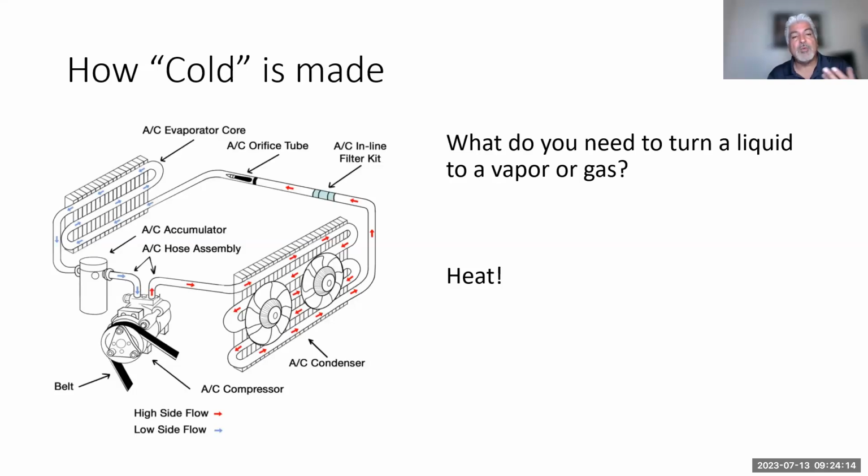What do I do, right? So in this case, it is a wise idea to look at the accumulator. And on most accumulator systems, it is the easiest component to remove and look at. So we can drain it to see the oil content, right? We can drain the oil. So let's say the system takes 8 ounces and I take the accumulator off. I'm looking for any contamination. But then as you pour it out, if you see metal flakes or desiccant material coming out, then you definitely have to replace the accumulator.